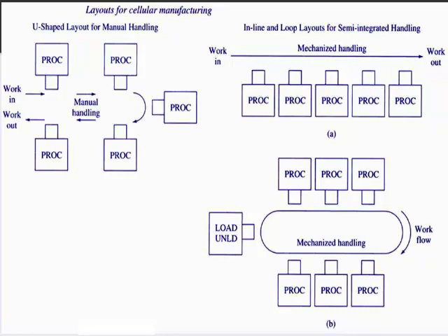The machines or processing stations are kept side by side all along the line. When the work part transfers from one machine to the other and stops, the machining takes place automatically. So the work part transfers for some time and stops for some time. A conveyor belt with intermittent stoppages can be used as a material handling or transfer device.